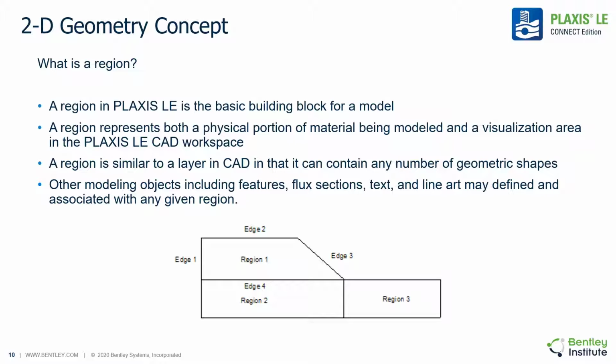There are also unique considerations of edges given in the slope stability software package. For example, the dynamic programming algorithm needs to have a definition of the series of edges which make up the upper ground surface. Many of these edge definitions are handled automatically by the software through algorithms which run in the background. These algorithms are designed to make the entry of the geometry easy.